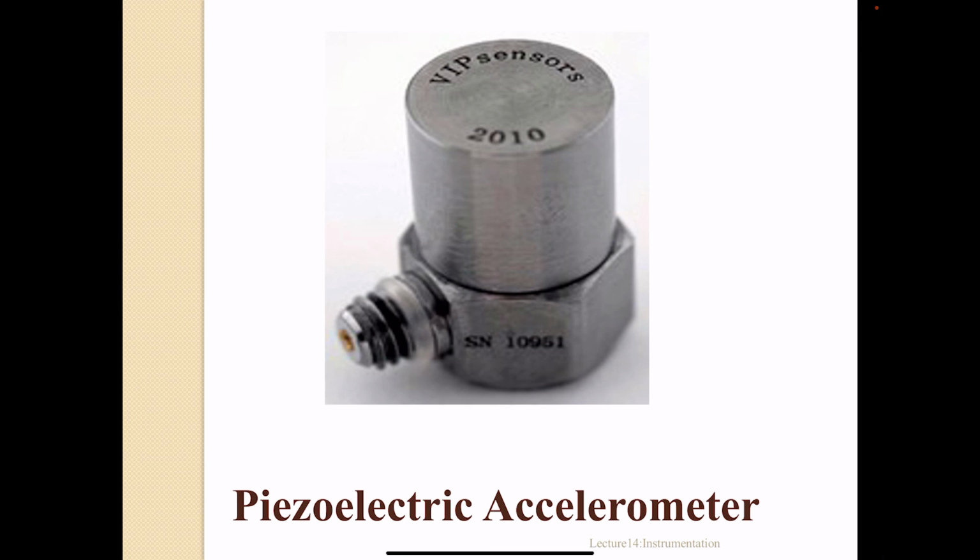So this is the piezoelectric accelerometer, where it shows the housing. In the housing there is a mass and also a crystal. When the piezoelectric crystal is stressed due to the acceleration force, it will produce an electrical output proportional to the acceleration.